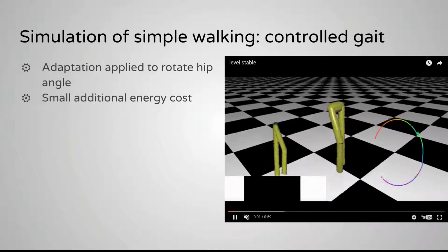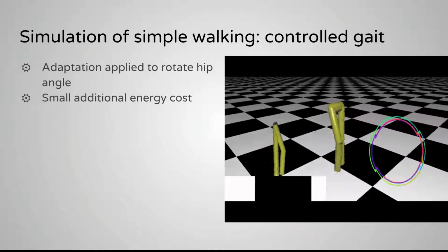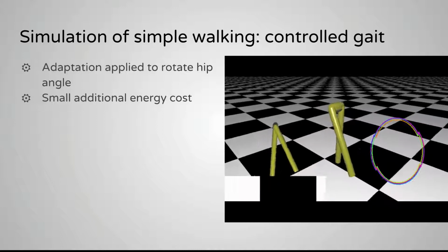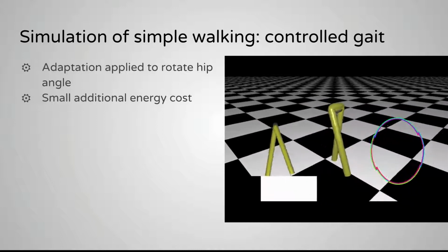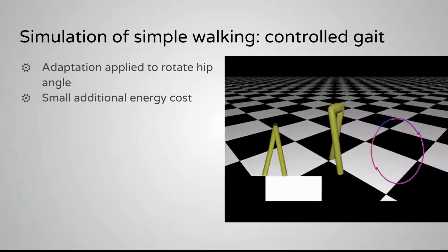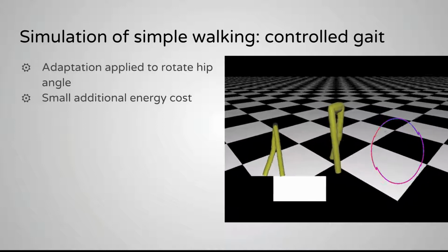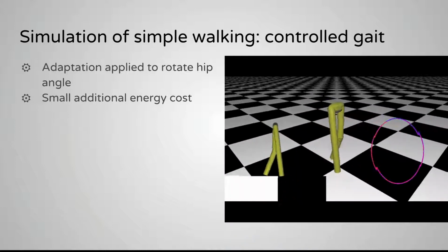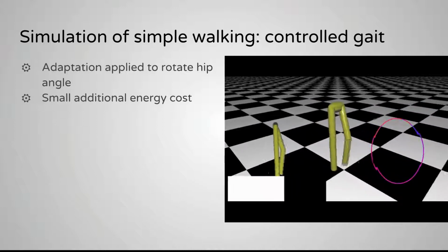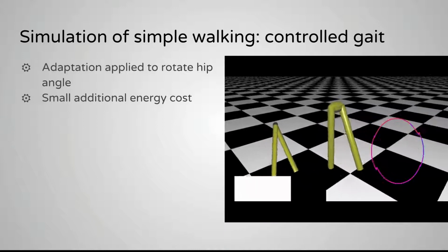So what we want to do then is apply one of our symmetry preserving transformations. The transformation is going to shift the robot, so apply an offset just like what we had on the human walker, and rotate the hip angle. So now our robot is walking on level ground, and I don't know if you can actually see it from the example, but it's slightly tilted backwards, which is quite possibly what we're doing anyway when we're walking on a slope or on level ground.